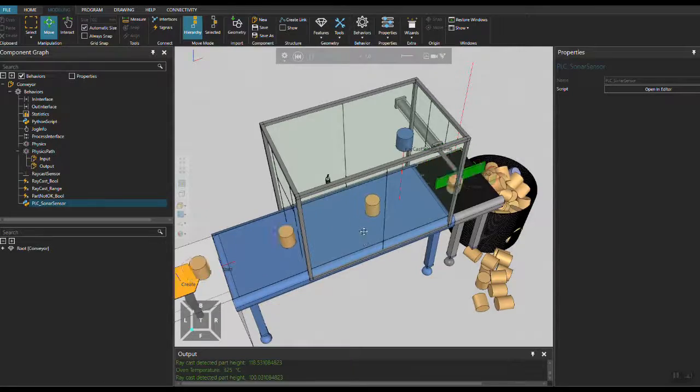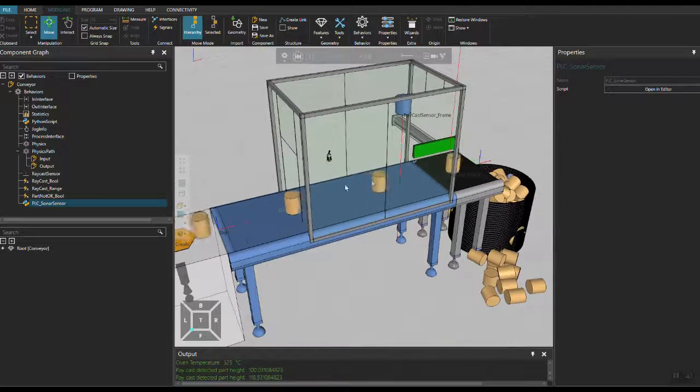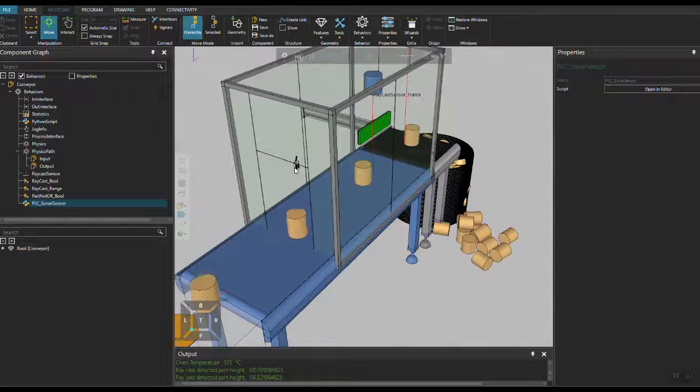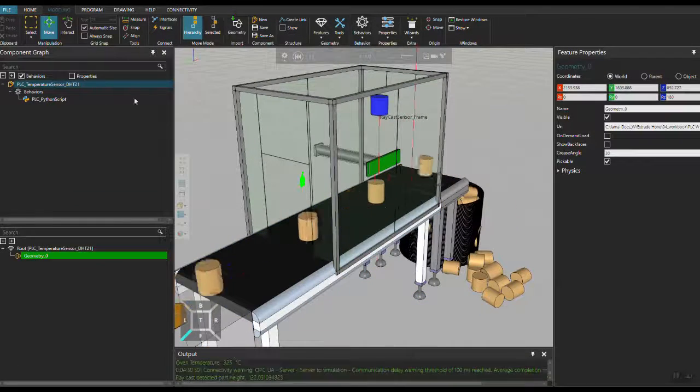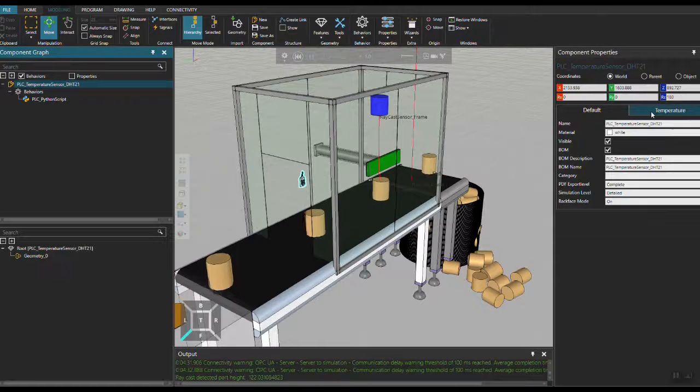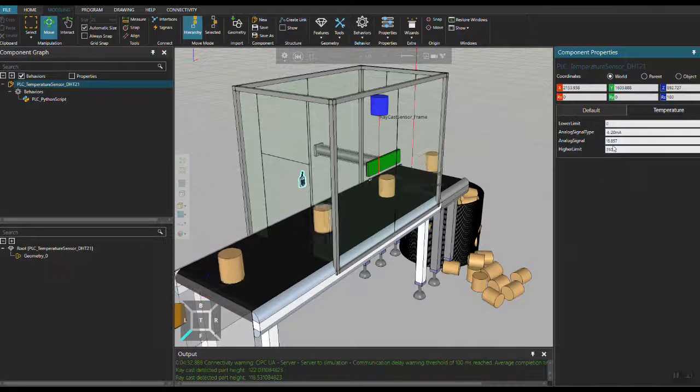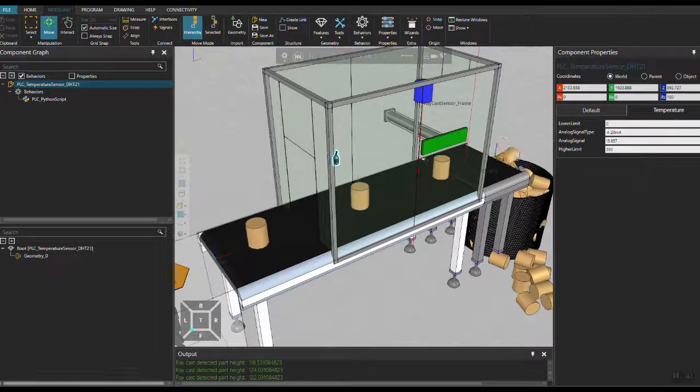The second condition is if this oven heat goes below a limit, so I would like to select this one, and you can see the temperature. It's an analog signal, between 4 to 20 milliampere as per the code.